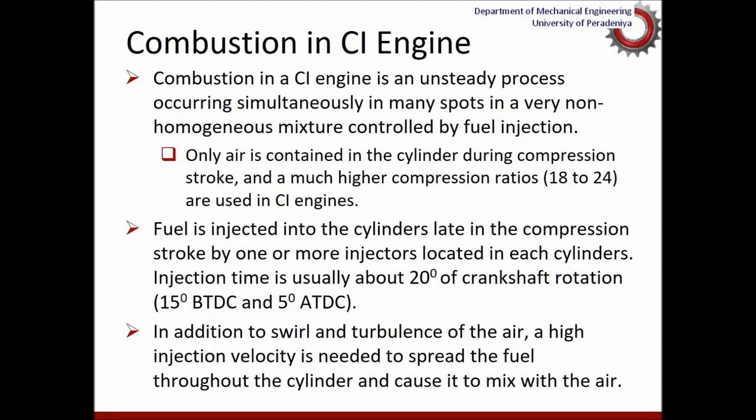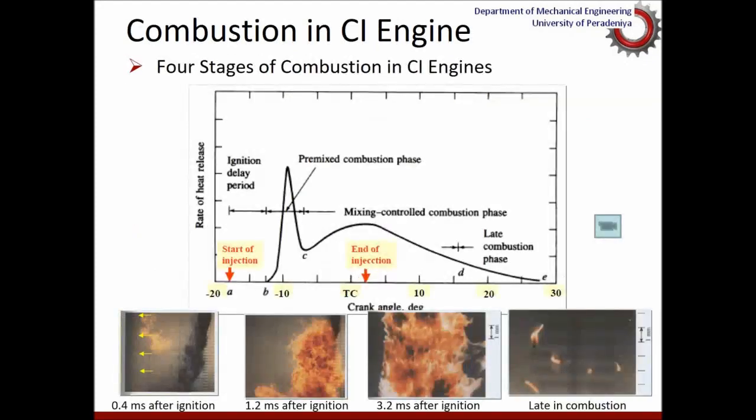Of course, in addition to the push, tumble and swirl that we generate, and the turbulence as a result of that, we need very high injection pressure or injection velocity to spray fuel into high pressure air for proper mixing and combustion to take place.